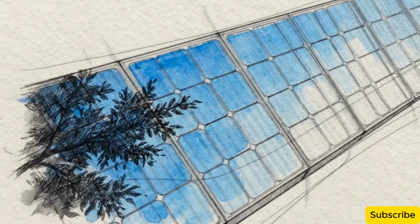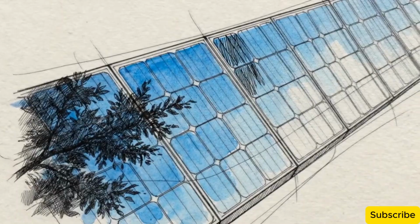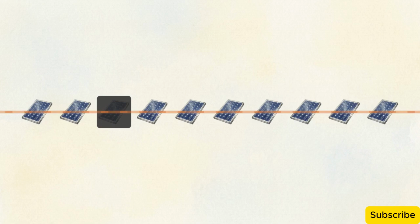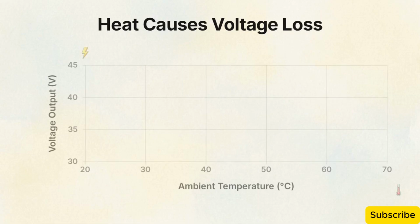The same rule applies to partial shading. A shadow from a single nearby tree branch or utility pole can choke the current flow and reduce the production of an entire string of connected panels. Then we have the heat paradox. While solar panels require direct sunlight to function, extremely hot, sunny days actually lower their operational efficiency.